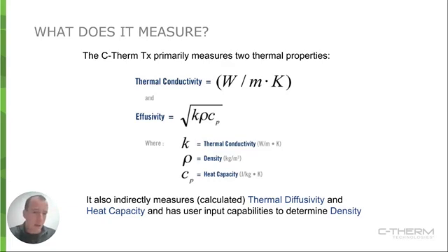And the main thermal property we're interested in here from the textile perspective is called thermal effusivity. Now, if effusivity is a newer term to you, first off, it's not emissivity, which is an optical property of a material and is not related at all. Thermal effusivity, sometimes called thermal inertia, is described as a material's ability to exchange heat with its surroundings or with other samples in contact with it. So it is the thermophysical property that determines the touch attribute or the touch sensation in coming in contact with it. It's defined as the square root of the thermal conductivity, density, and heat capacity.